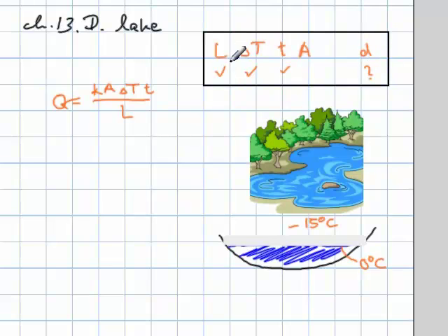When I look at these, that gets me to the equation for heat conductivity. And then I notice there's an A. They don't tell us how big the ice sheet, how big the lake is. So I'm writing this down here without a check mark, but I'm figuring out that somehow it will divide out. We'll see. The K here, of course, is given. That's the conductivity of the ice. In this equation we don't know what the area A is, and they don't tell us what the heat flow is. So we have two variables with one equation, and we really can't do anything at this point.